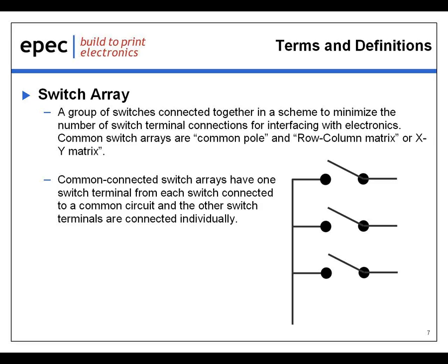When more than one dome switch is assembled into a keypad, the resulting combination is called a switch array and is a mechanical or physical layout as seen by the end user. What's not seen by the end user is the method by which the switches are connected together electrically. Obviously, individual switches are not required to be electrically tied together in any way. However, the number of circuits from the dome switches can become quite large with larger switch arrays. For example, 20 switches that are not connected together require 40 circuits, or 2 circuits per switch.